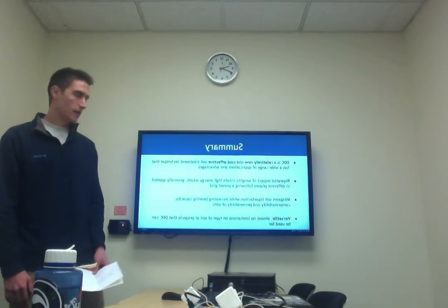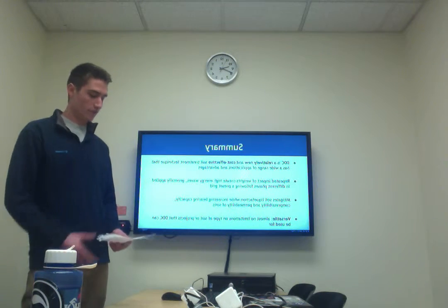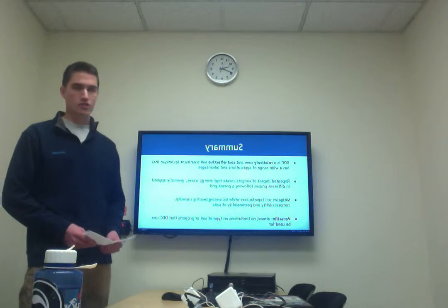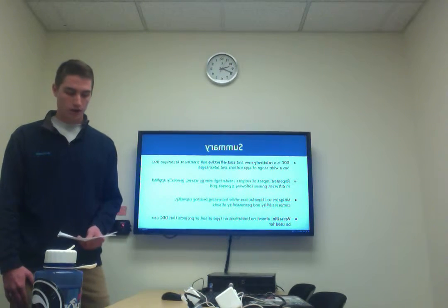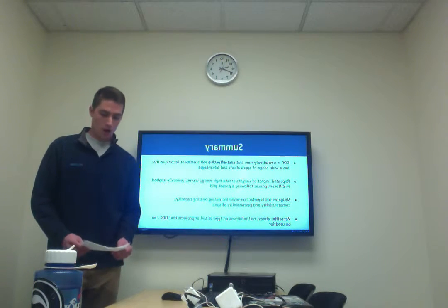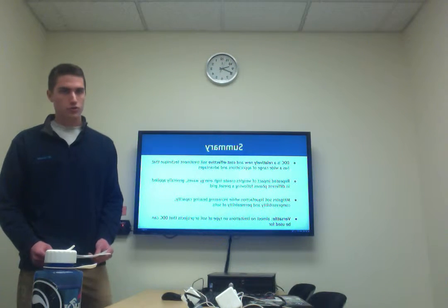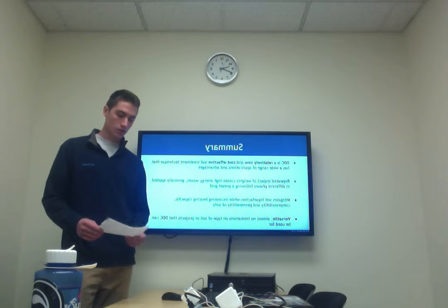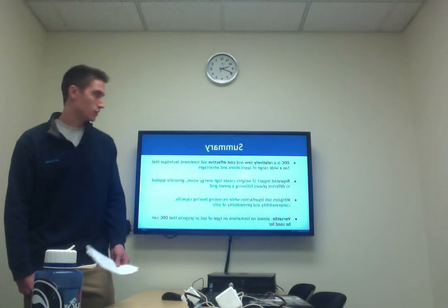So now we know that deep dynamic compaction is a relatively new technique. It's around the last 35 years. It's also a cost-effective soil treatment technique that has a wide range of applications and advantages. As Richard stated before, it could cost as much as $1.50 to $2.75 per square foot. This depends also on the site and the geographic location of the project. Looking at other soil treatment techniques such as lime stabilization, which can cost as much as $4 per square yard or $35 per square feet, this is relatively cheap.